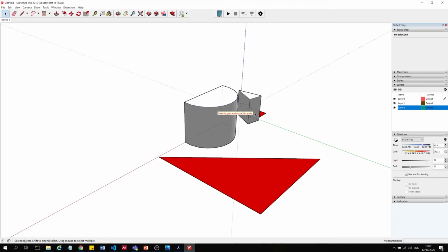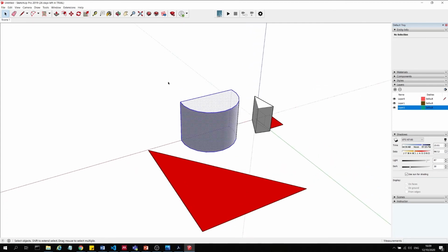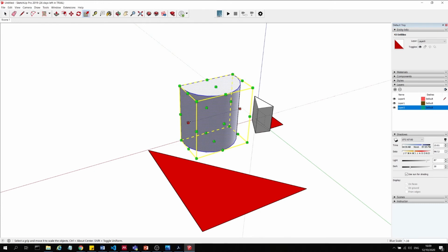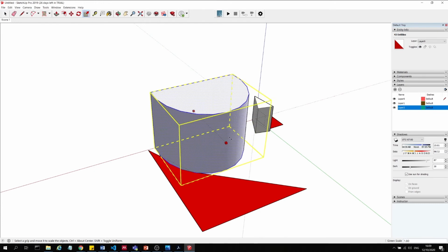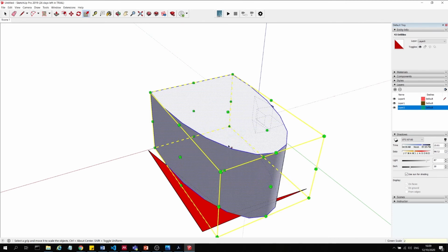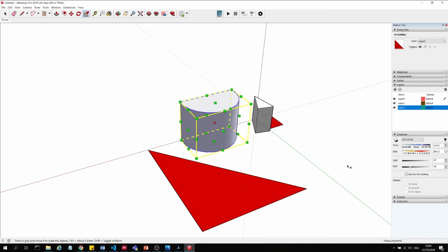And if I select on my 3D objects like here, I can also scale that in 3-dimensional in different ways. So I can scale it like this, or however I want. I can also input the specific scale that I want here. So if I want to scale this by 2 times, I just type in 2, enter, and now that's scaled 2 times the size. So I can Control Z to undo.